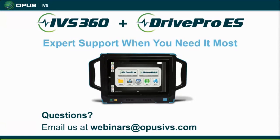Exactly. Now, one thing I would like to note, for anybody who's watching this chat, go to the Files tab. In that Files tab, you'll see two files, and those are what Andrew was talking about, put-together documents with normal known good crankcase vacuum specs, taken generally with a digital manometer at the oil cap or at the dipstick hole.